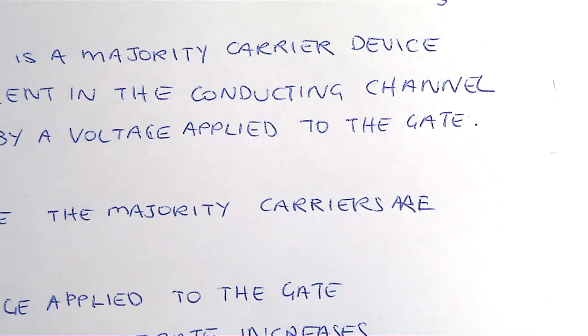Depending on whether you want to go to higher frequencies, you might add some more capacitors here. You might add an output resistor here to contend with channel length modulation. And you might add a few other bits and pieces. But here, essentially, what you're assuming when you calculate using that particular model is that the voltage between the gate and the source, this is source and this is the drain, is relatively small.